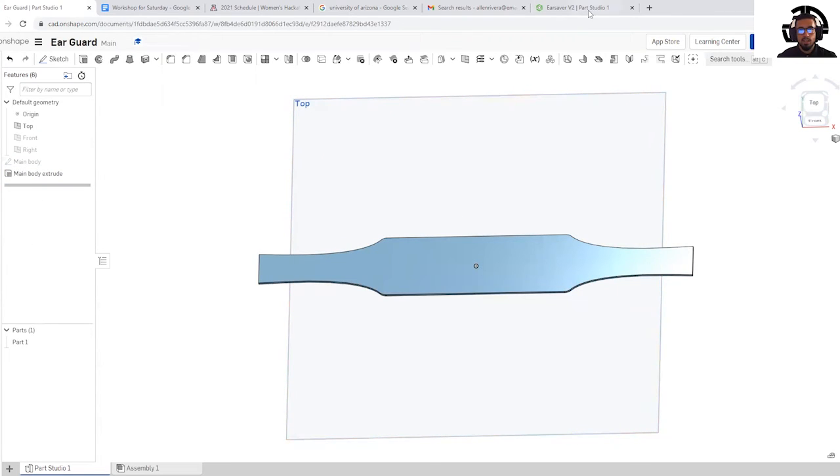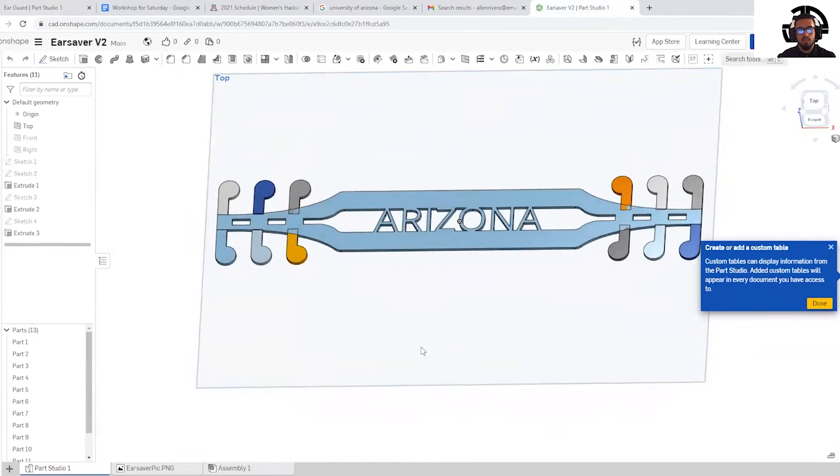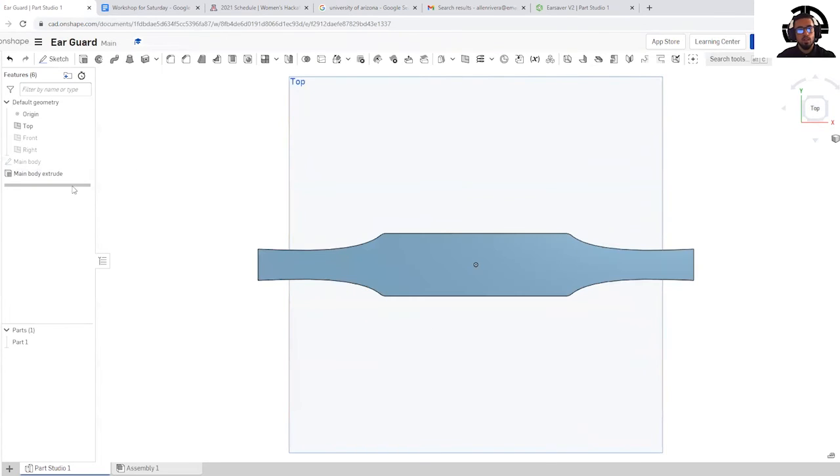So in the other version, you see that I have these little points of attachment for the mask to hold on to. So it'll stick right in here and then it'll catch on and it'll be under tension. So that way it's pulling outwards and it won't necessarily release. So what I want to do is I want to incorporate that onto the sketch. But now how do I do that? So I'm going to actually suppress this because I want to work off of this flat plane.